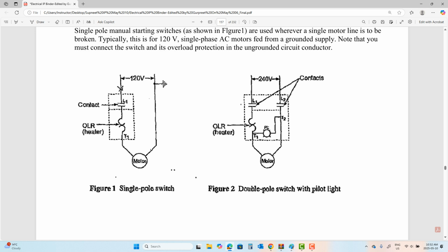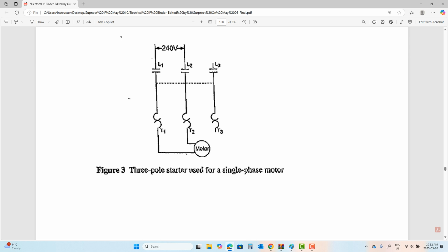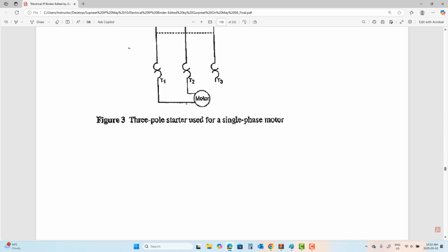If I have a single phase motor, where are my overloads located? Always on the phase, never on the neutral, right? So on the phase, I will throw a relay which will act as an overload device. A dotted line means a relay, shown as a combination of a coil and a contact. If I have two inputs going in, do you see? One relay, second relay, a motor control. So two phases, two overloads. If you have three phases, how many overloads will you have? 3 overloads. Means 3 relays. Each phase will have one relay. We keep going.